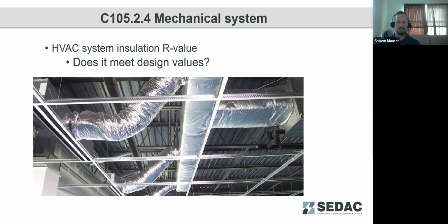Next is checking the insulation R values for commercial buildings. If it's outside conditioned space, does it have the proper insulation values for the area it's located? If it's outside the building, is it R6, R8 insulation at a minimum? And also verifying, is that ductwork properly sealed underneath?